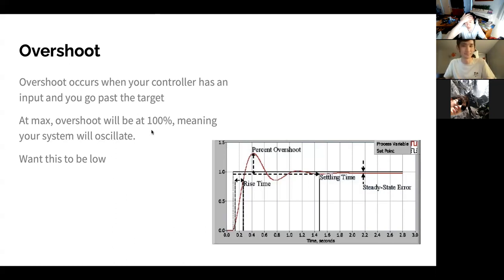Yeah. In addition, this overshoot value and the damping behavior that you see in the image on the right, that's an ideal situation, right? So ideally there's no external factors that would affect the flight of your quadcopter. And so it can overshoot and then dampen itself out over time. But unfortunately in the real world, whether a fan is blowing or your motor duty cycles aren't perfect, that overshoot can cause insane oscillations if the conditions are really poor, and that can cause your quadcopter to do a complete flip, and that would be suboptimal.